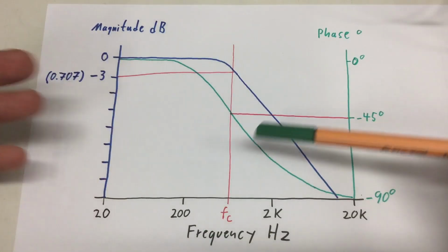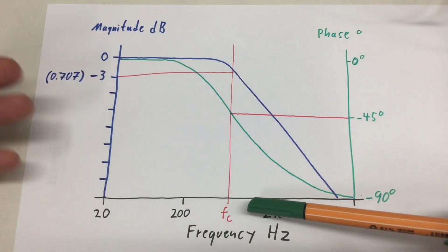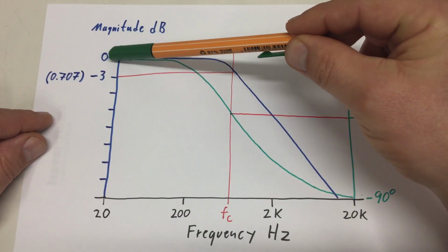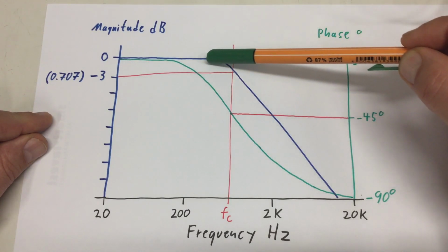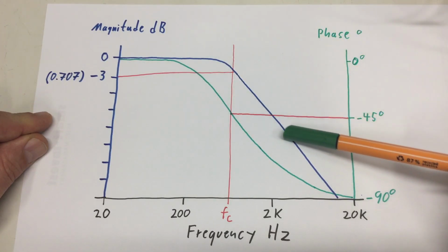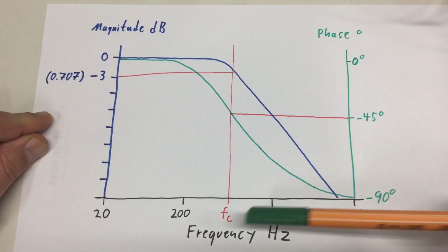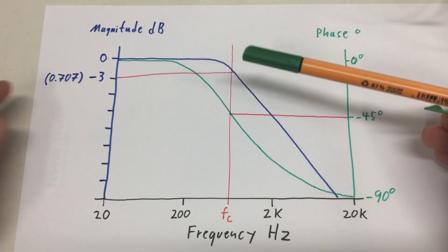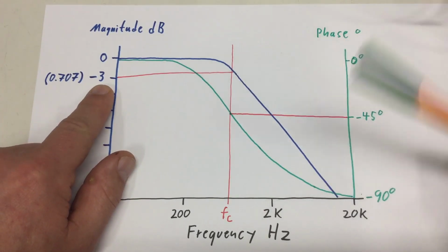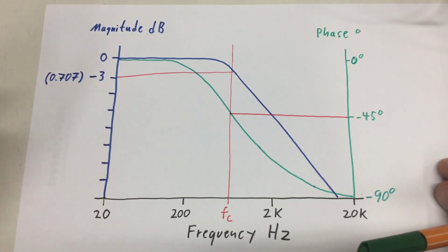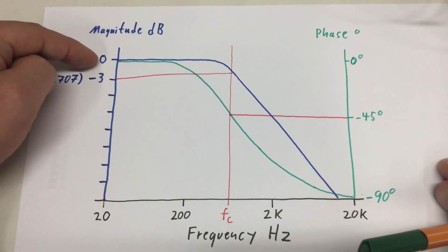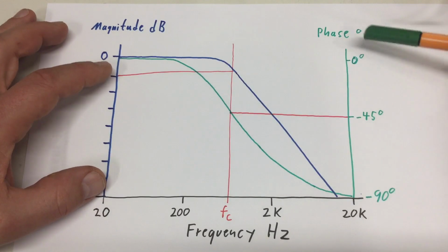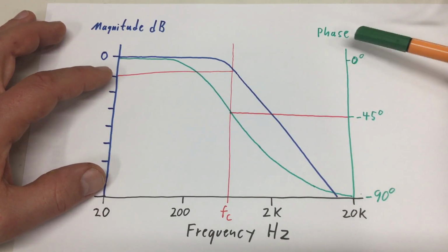So what we've seen here, my RC low pass has some frequency it's operating on. And if I increase the frequency, my magnitude at one point starts to drop. Okay, and the frequency of the RC low pass, that is when we reach minus 3 dB, or 70.7%, or 0.707 of the magnitude of the input signal.